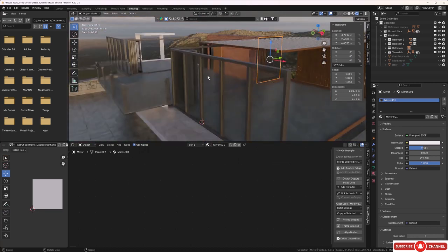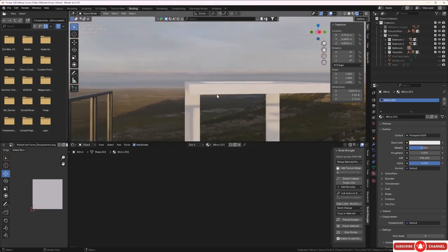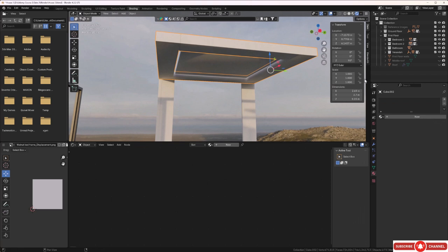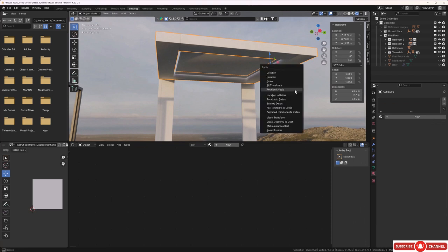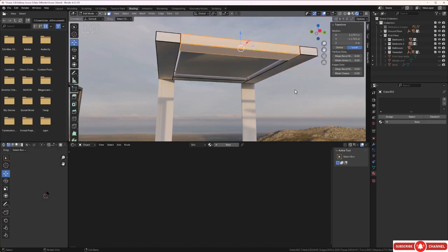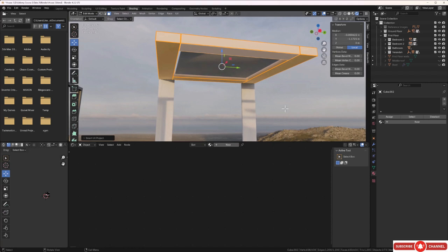Okay, so the next thing to do is head over to the other bedroom now. So I'll move over there and I'll press Shift B and I'll recenter Blender on this one here. And let's see what we're going to do with this. So I'll grab this top bed frame here, check the scale and the rotation's out. So I'll press Control A and apply rotation and scale. And now let's go ahead and tap into edit mode with it. And we'll press A for all. And U, and we'll go for a Smart UV Project and we'll unwrap. Let's zoom in on the UV map so we've got that right.